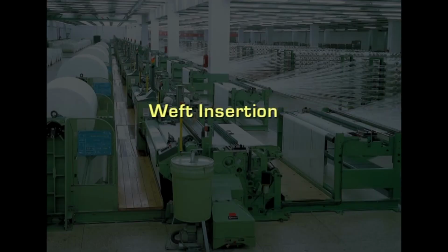Now, the weft insertion. In an air jet, the weft yarn is carried by pneumatic means. The shed opening should be very clear. Even a small hanging thread in the warp sheet will stop the passage of the weft yarn. Here you have a jet of air that actually takes the weft flying off from one end to the